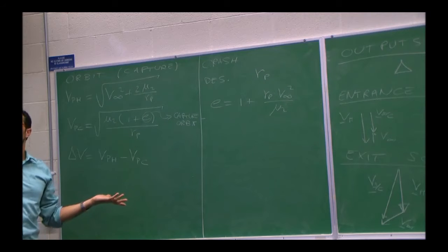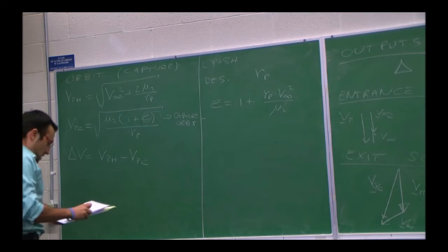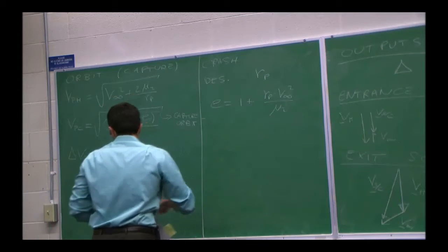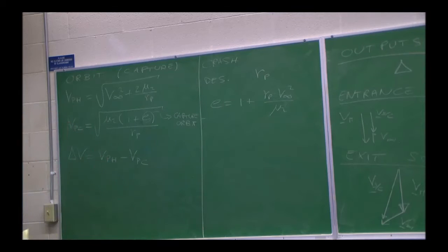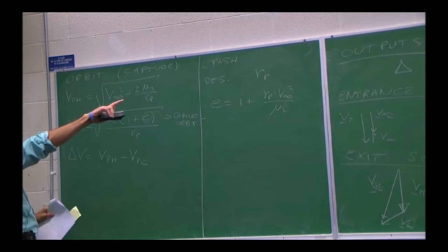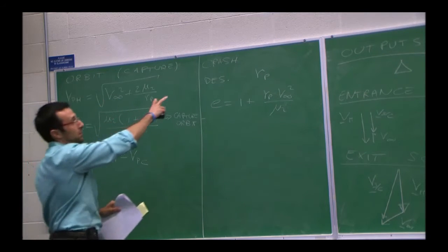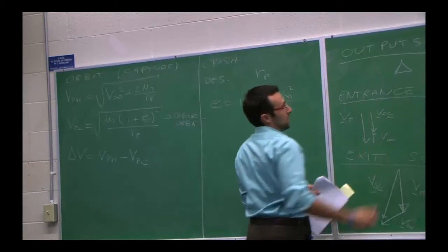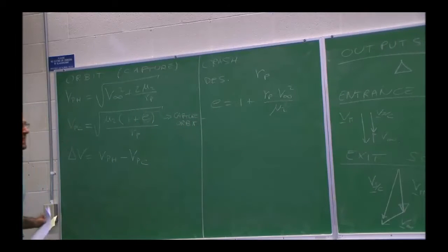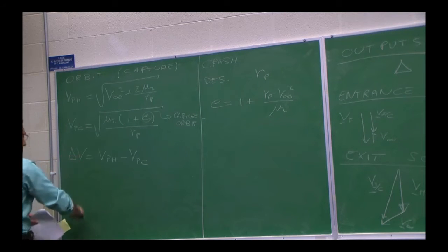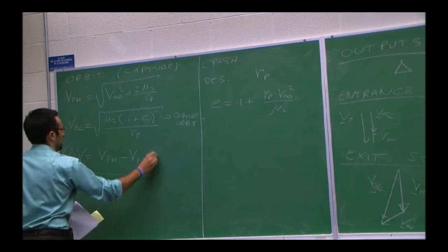You're doing nothing. Okay. So what your book is doing is trying to find what is now the correct Rp, the distance at perigee, which again, once you have Rp, you can always bring it down to the aiming radius. What is the Rp I need and the eccentricity that goes with that on the capture orbit so that this delta V is minimized? Of course you want to minimize this, right?